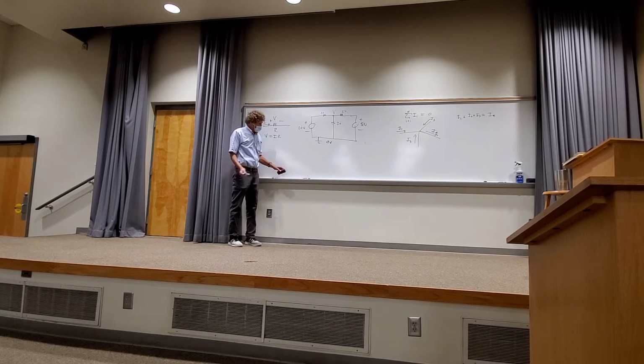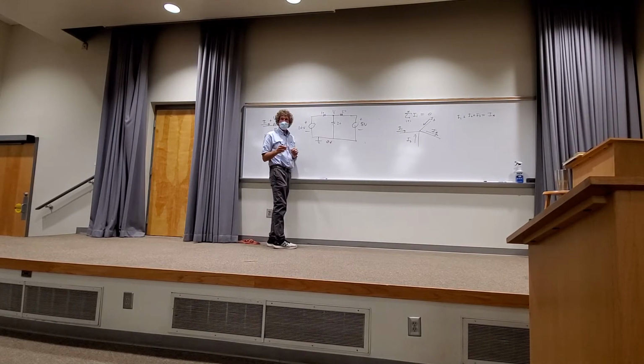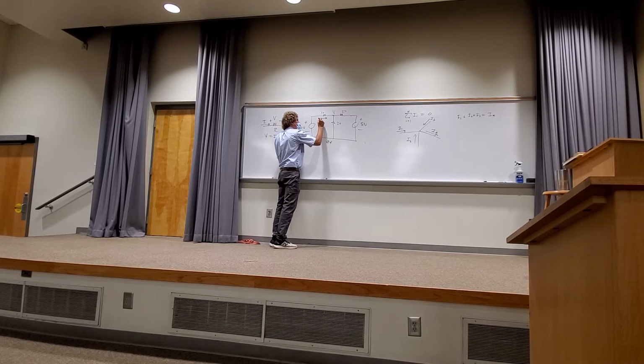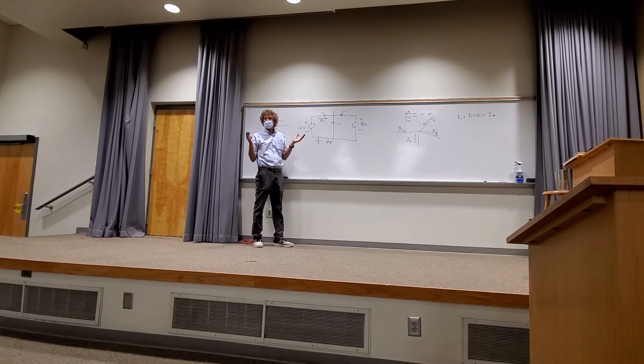All right. So I've got that. And my job here is to find that unknown voltage. I want to see by analysis techniques what that voltage is. So here's how I do it using nodal analysis, or Kirchhoff's current law. The current here, I'm just going to arbitrarily call it I1. Doesn't matter what I call it. Doesn't matter the direction.